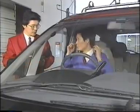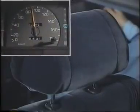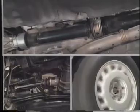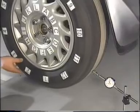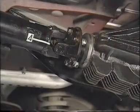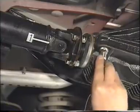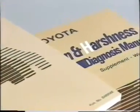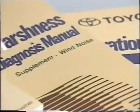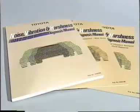Please remember two important rules of troubleshooting. 1. Identify the symptoms of the problems accurately by listening to the customer and by test driving the vehicle yourself. And 2. Search for the vibrating force and vibration generating mechanism in accordance with the principles of troubleshooting. We hope that this video has been useful to you. Please refer to this video and the NVH diagnosis manuals at all times to correct NVH problems accurately.